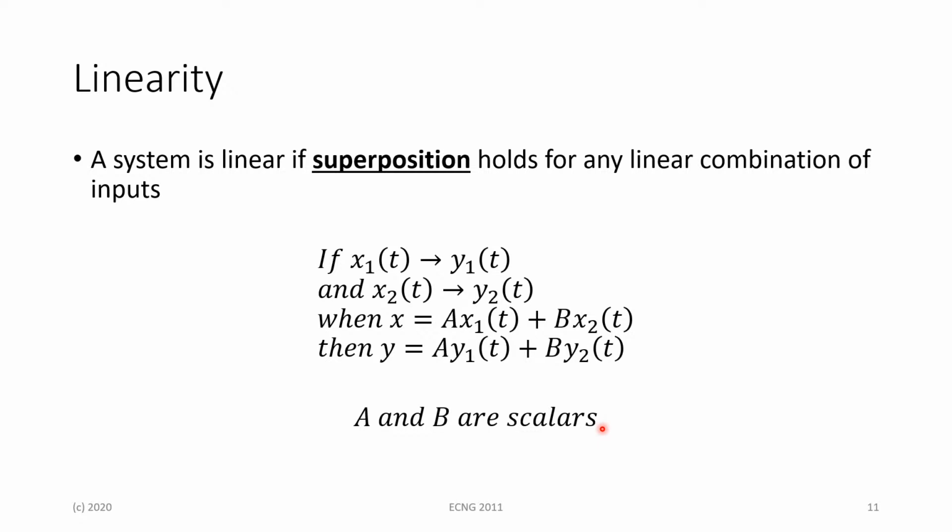Alright. So for linearity, basically what this means is that once you have your mapping between x1 and y1 and x2 and y2, if you apply the addition of the two signals multiplied by any scalars, being a and b here, and you can prove this mapping exists between x and y, you can prove that your system is linear. And what this basically means is that once you have a system of order 1, meaning that you have no squares or cubes and so forth, your system is going to be linear. Once you start going off in increasing orders, that means your system is non-linear.